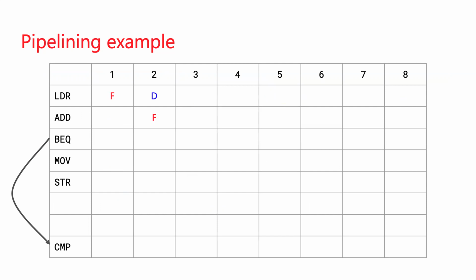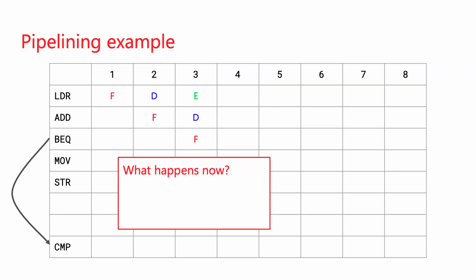And then, so I didn't say this, but we'll pretend the horizontal axis is time. I know that was on the slide, but I didn't say it. And so once we've decoded the load instruction, we can execute that, and we can start decoding the add instruction and fetching the next instruction. And we can keep on doing this. The problem is when we get to this break. We can have a bunch of instructions, even if some of them take multiple clock ticks to execute, as long as we can keep this pipeline saturated, then we can finish executing one instruction after another in a single clock tick.